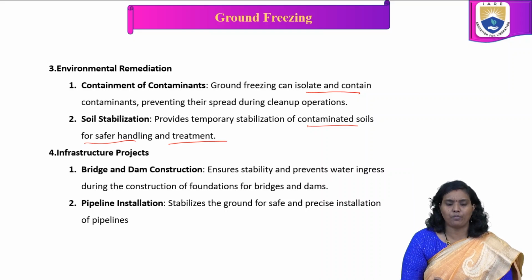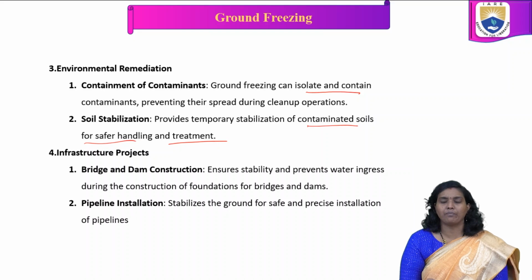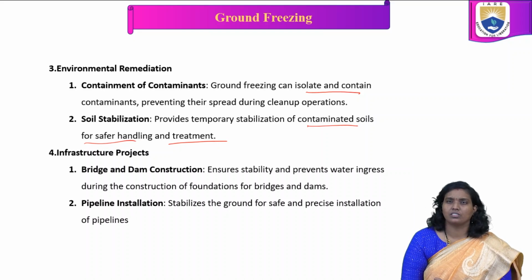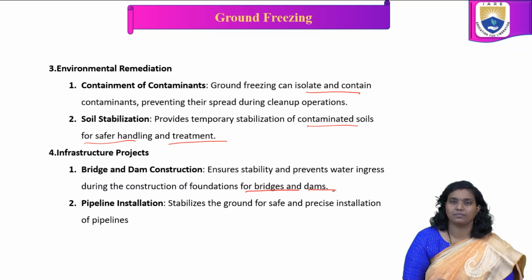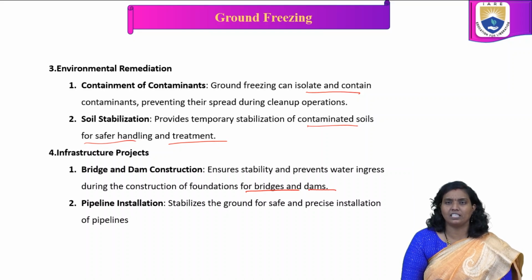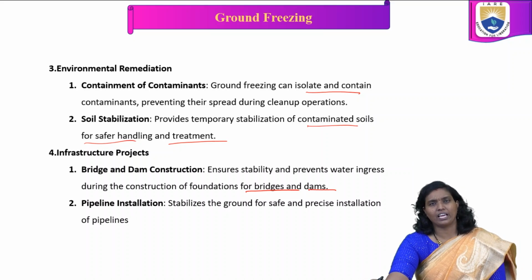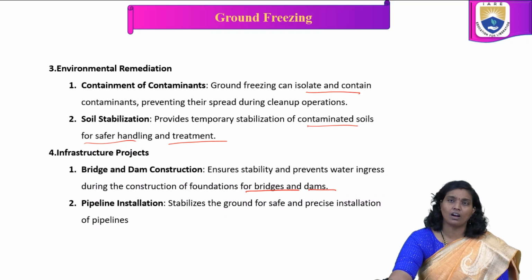In infrastructure projects, bridge and dam construction: it ensures stability and prevents water ingress during the construction of foundations for bridges and dams. In pipeline installation, it stabilizes the ground for safe and precise installation of pipes. So, these are some of the applications where we apply ground freezing.